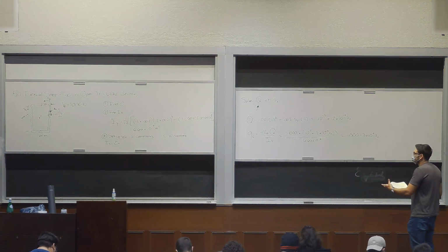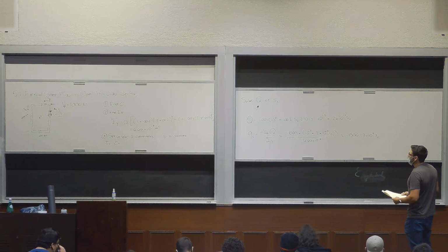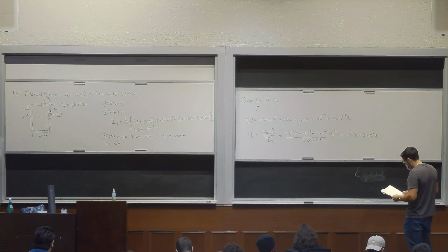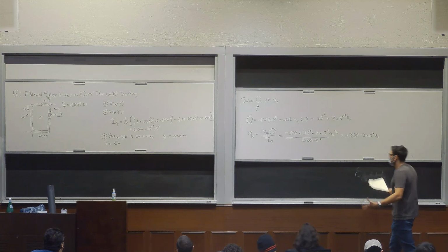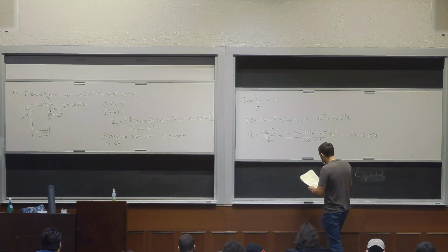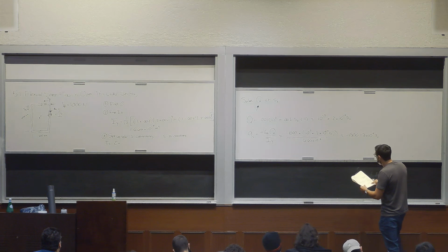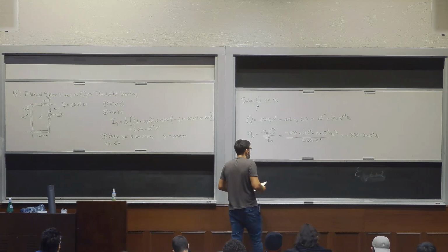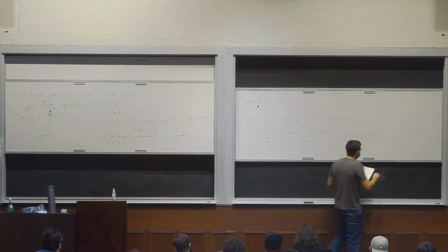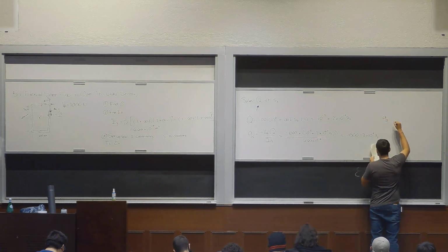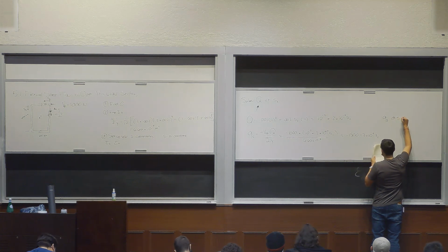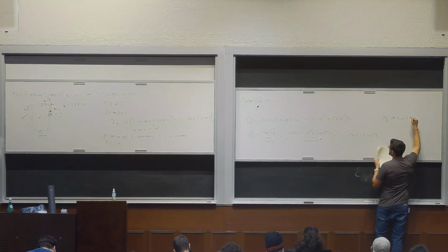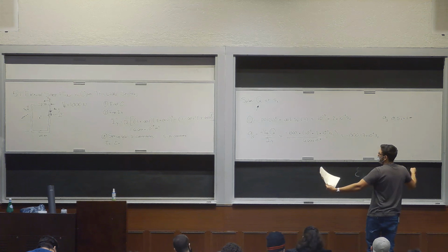And as you can see, it's a linear distribution as opposed to that vertical portion where it was parabolic, quadratic. All right, and then we do this whole same process again. Actually, before we do that, we find the maximum Q S, so Q S at S2 equals 0.1, because that's the width of that structure.